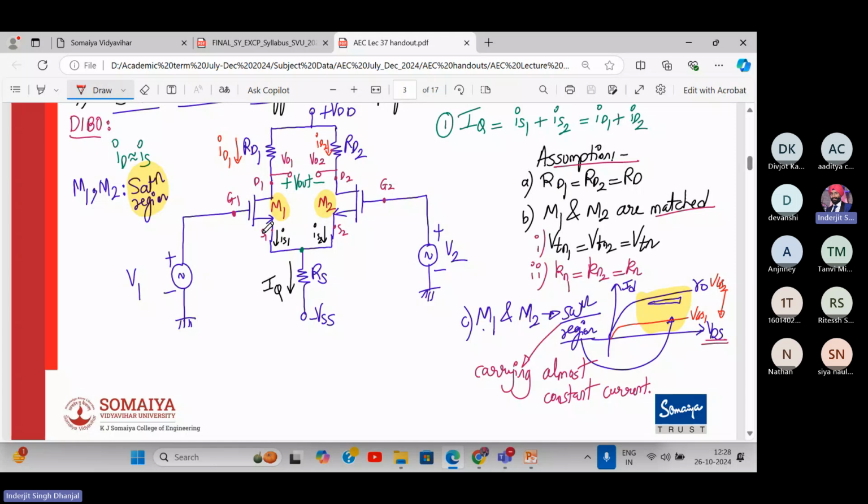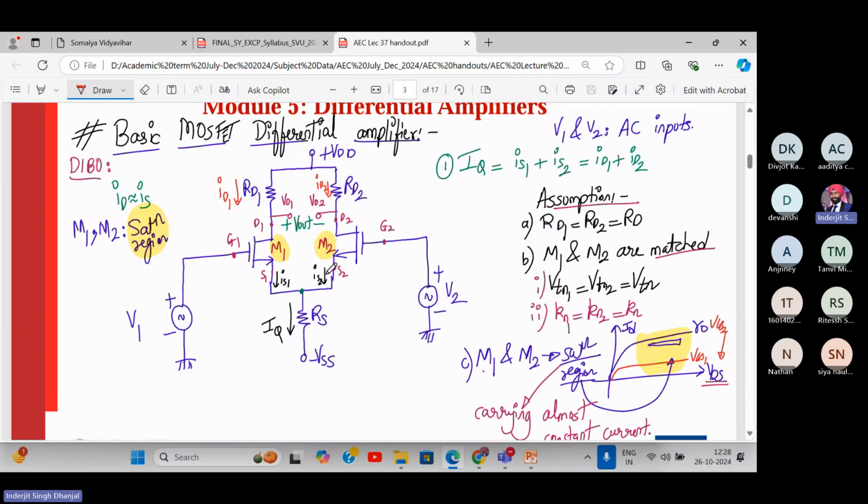The basic MOSFET differential amplifier uses both positive and negative bias supply. This is the clue actually. Because of the positive and negative power supply, it eliminates the need for any coupling capacitors or voltage dividing biasing resistors. As you can see, there are no voltage dividing resistors externally connected. So this type of amplifier is called a directly coupled amplifier, which does not require biasing resistors.